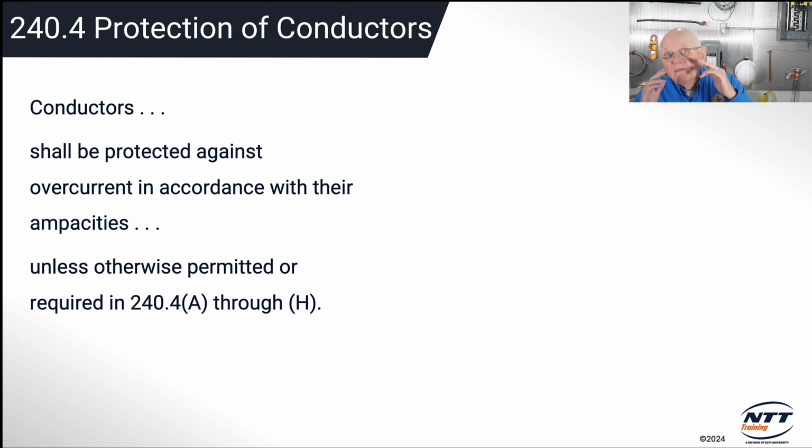So that takes care of 2 of my 3 areas for overcurrent protection. Back in Article 100, the definition for overcurrent, the third type of overcurrent condition that I can have is an overload, where my motor starts to draw just too much current for whatever reason. It starts to draw more than what it's rated for, and it'll probably carry that for a period of time. But after some short period of time, that motor's going to trip on overload condition.